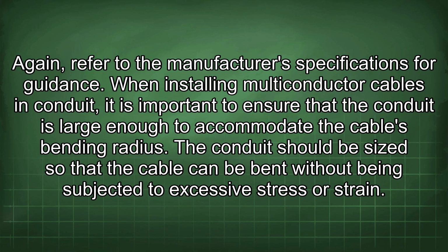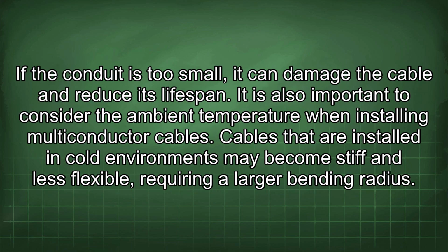When installing multiconductor cables in conduit, it is important to ensure that the conduit is large enough to accommodate the cable's bending radius. The conduit should be sized so that the cable can be bent without being subjected to excessive stress or strain. If the conduit is too small, it can damage the cable and reduce its lifespan.